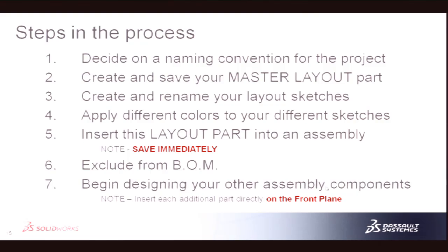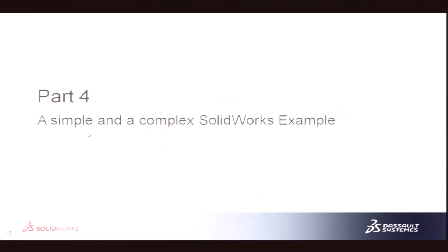And you can see here, you're going to begin designing your other components, and you're always going to insert your components on the front plane. Now, of everything in this technique, that's the only one that's a little weird. It takes a little getting used to, but after you do it a couple of times, it's a piece of cake. And it makes sense. All right, so a simple and a complex SolidWorks example. We're 20 minutes in. We're at part 4 of 5, so we're doing great for time.